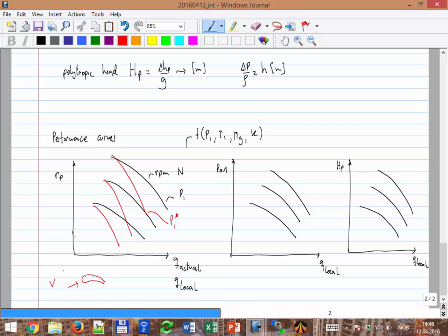If we have the same volumetric rate but we change the density, then we are changing the velocity. So we are changing the performance of the machine. To put it simply, it is because you're changing the density and the properties of the fluid at the inlet or incident to each blade stage.